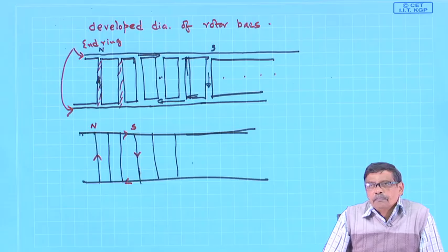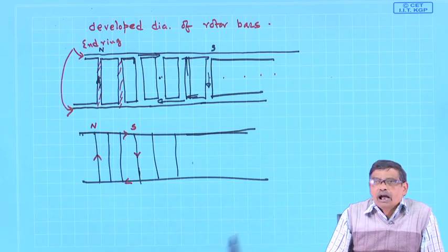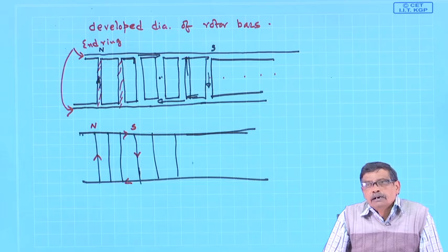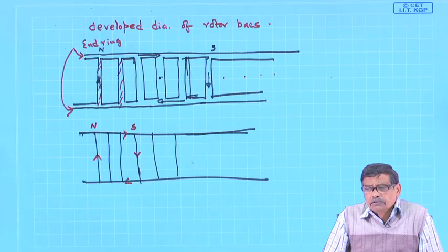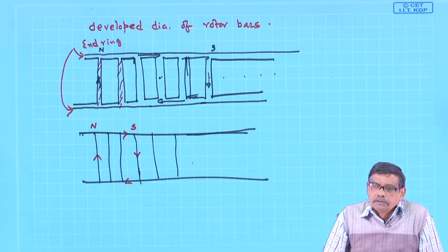But it is possible, which I indicated while discussing my winding layouts, that you use the same winding which is wound for say 4 poles, and reconnect the winding groups such that it will produce 2 poles. That is the new thing now.